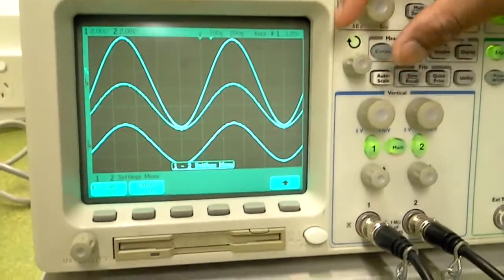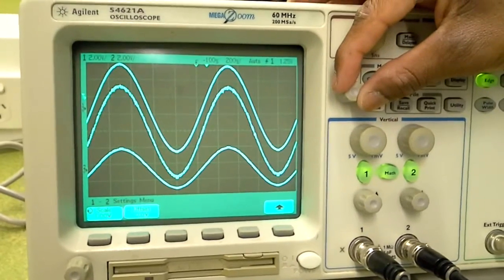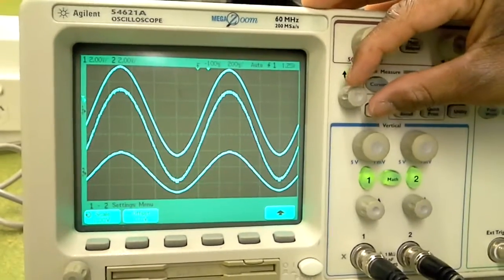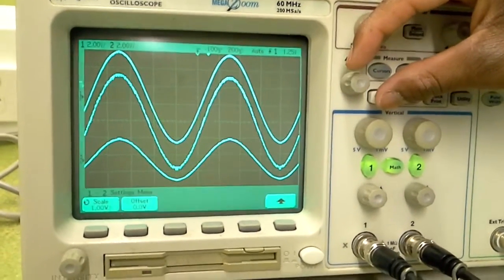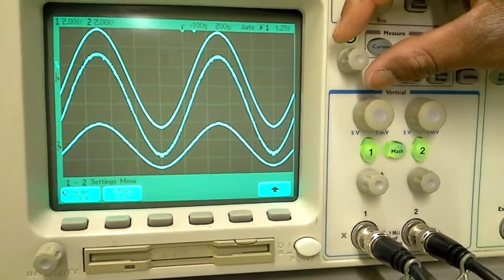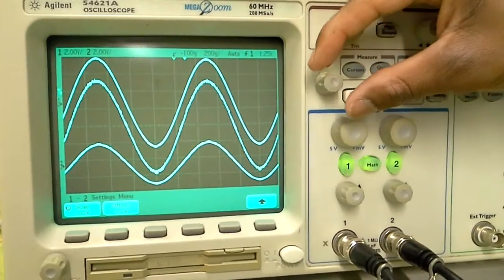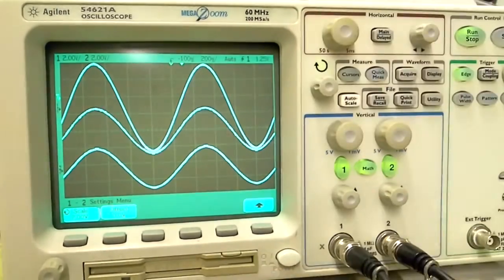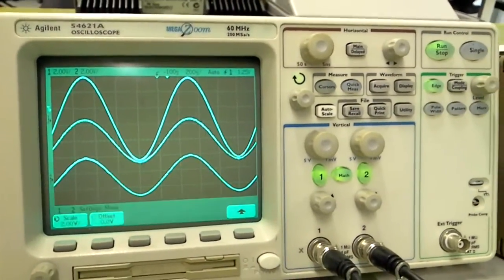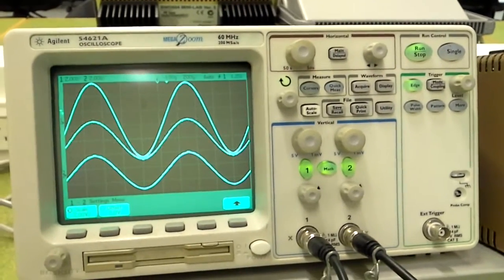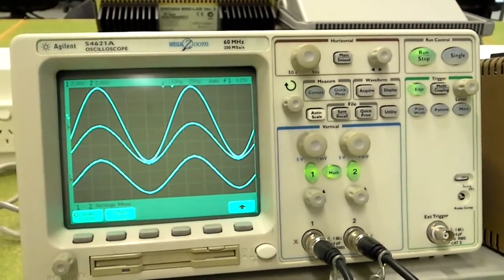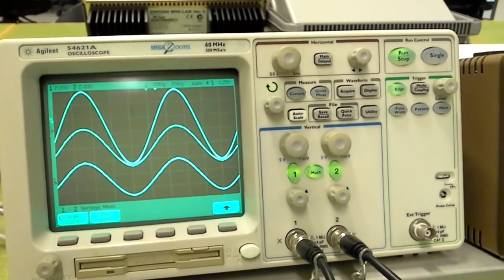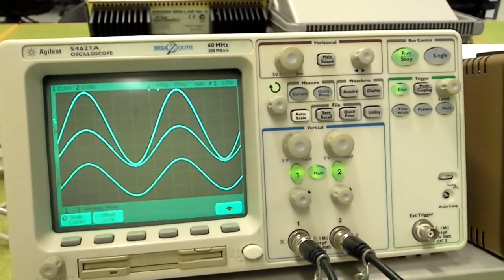So here the scale is 2 volts. We can change the scale to 1 volt, and as I change the scale, we see the amplitude swing increases. Actually the voltage remains the same, but because we choose to use a smaller scale, we see a larger voltage swing, and offset is 0. So to measure how much is the actual voltage, we need to check the scale, and we should set the offset to 0 unless we want to add any offset to that voltage waveform.